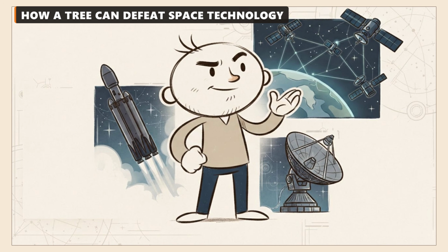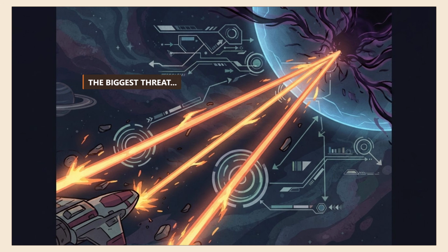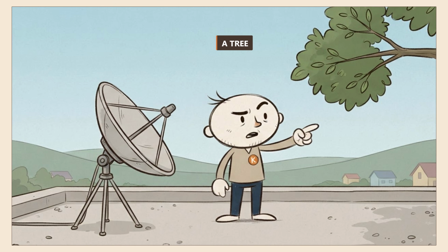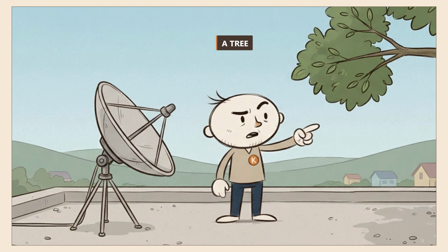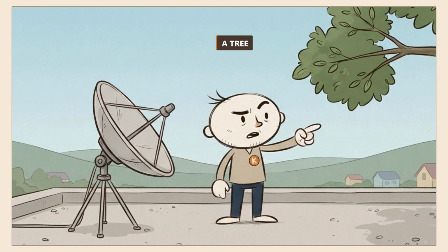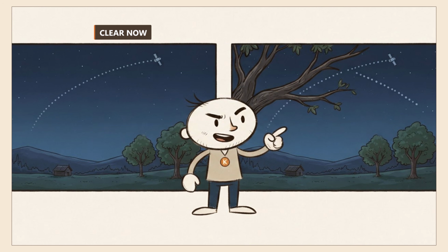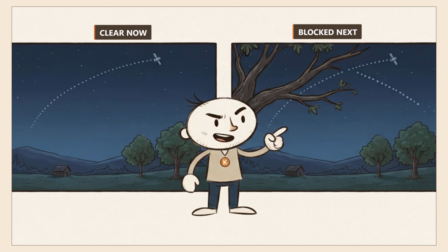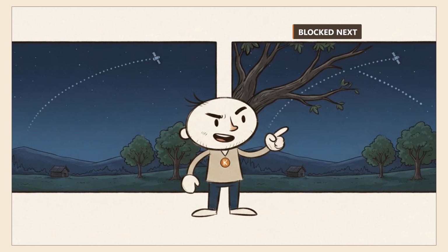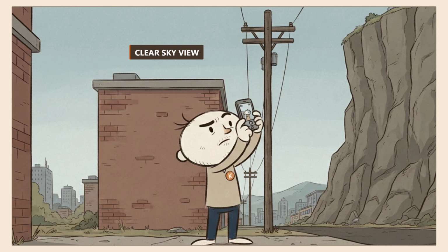Starlink uses rockets, thousands of satellites, phased array antennas, automated routing, and space lasers. Its most dangerous enemy is a tree. The terminal needs a broad and reasonably clear view of the sky. Because satellites move, the dish must communicate through different parts of that sky. A branch may not block the active satellite now. 30 seconds later, the next satellite may pass directly behind it. The system can try another satellite. But if a useful path is blocked, the connection can drop.